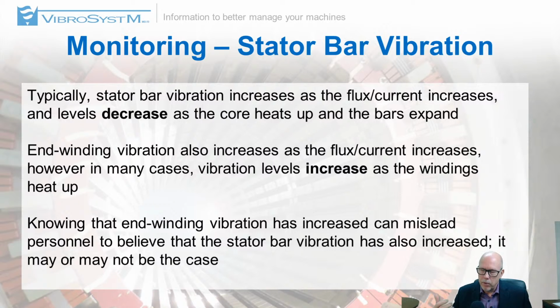It's important to remember when you heat up the windings and the stator bars, of course, the copper and the insulation will expand. And I get the question often, how come the end winding vibration is such a problem? I mean, can't they just make it stiffer? And the answer is, well, it looks very easy, but imagine you have to make a consolidated basket that is extremely stiff to prevent vibration, but it also has to be very flexible to allow the expansion and contraction to occur. So you have to make something very stiff and very flexible.